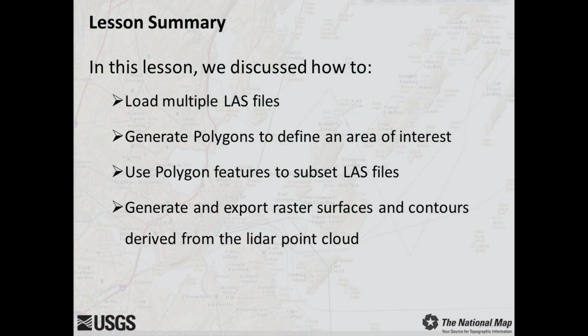This concludes Lesson 10C3, Clipping LAS Data and Creating Derivative Products in Global Mapper. In this lesson, we discussed how to load multiple LAS tiles, use polygon features to clip LAS files, and generate and export derivative raster surfaces and contours.